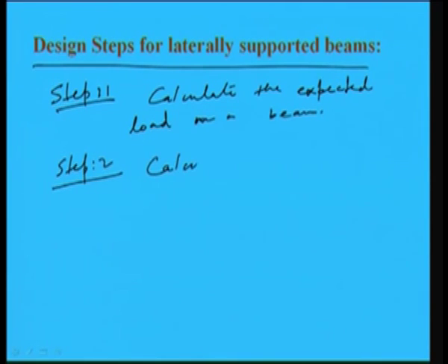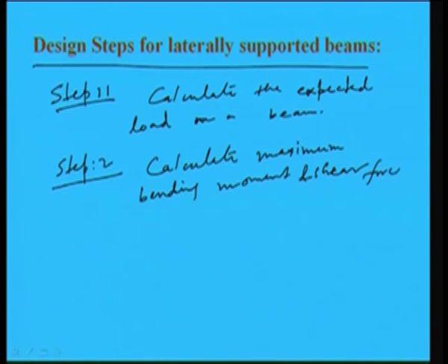calculate maximum bending moment and shear force. The moment we calculate the maximum bending moment and shear force, then we can find out the stresses due to moment. So, this maximum bending moment and shear force can be found from the loading condition and from the boundary condition of the beam. So, from there we can find out.